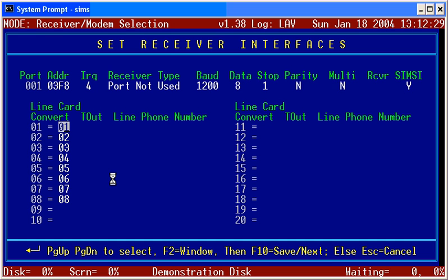So if you answer yes there, all of your signals will come through as a 2-digit zone. That includes SIA, Contact ID, Ademco High Speed, etc. If you answer no, then it's going to transmit it in the widest possible protocol with a couple of exceptions. Modem 2 is going to be transferred for single and 2 digits the way it always was, which was a single digit or a 2-digit. If you want to modify that to some other, there are several available options in there.